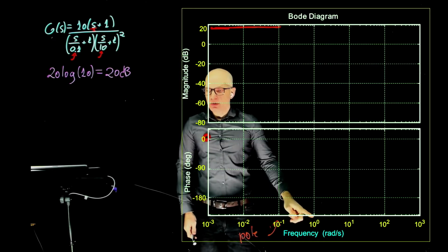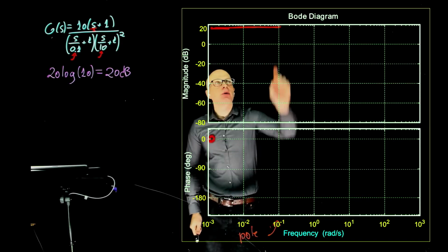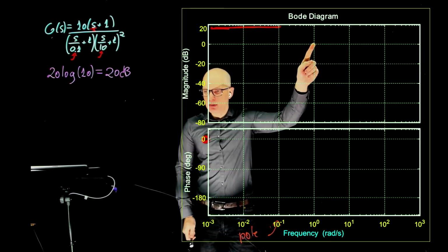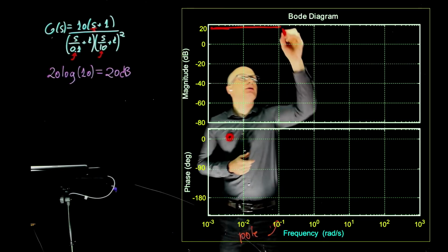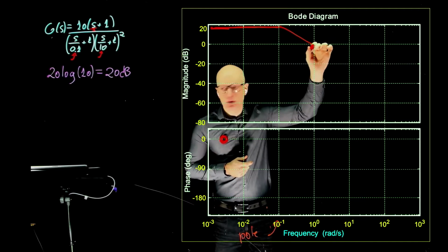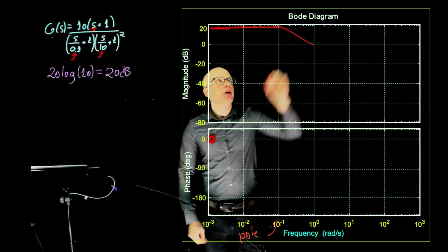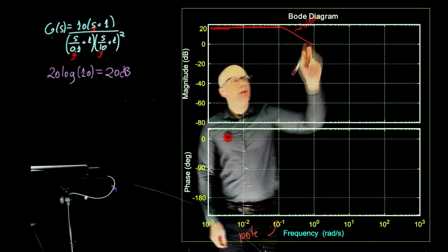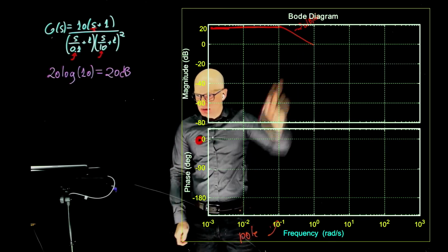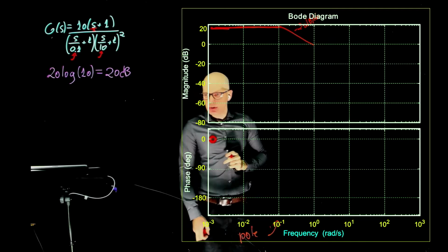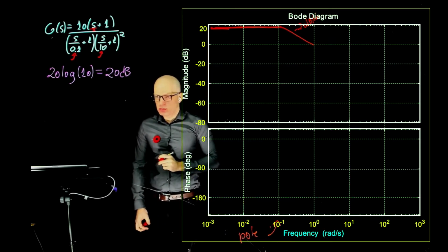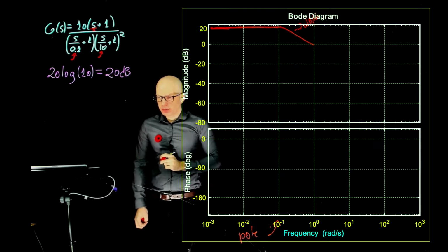So what is the magnitude of the Bode plot at 10 to the power of 1? If here we are at 20, we move on by 10, and that gives now a slope that it decays at a rate of -20 dB per decade. And now at 10 times this frequency, we reach 0 dB. Is this clear?